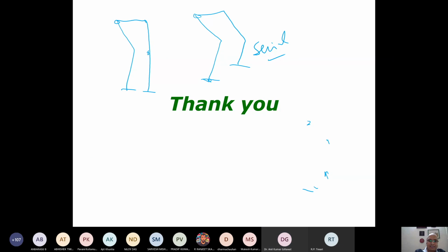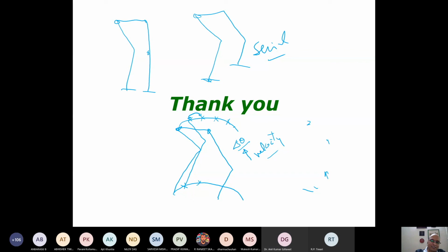So how do you get that? Essentially when it is walking, let me draw it here. This is my trajectory, right? In the trajectory, I'm dividing the trajectory into 20 points, right? So every point is corresponding to the other point for the hip and the leg, at the trajectory. Now, if you do inverse kinematics, when it is moving from here to here, the joint is also moving by a small amount del theta. So this is what I mean by velocity, incremental velocity.